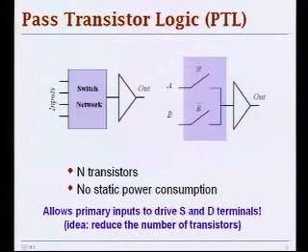So last time we talked about using transistors as switches. We already knew that pass transistors behave as switches, and we're pretty much switching VDD and ground to the output. So why not switch some other value to the output instead of just VDD and ground? As you can see here, we can save a lot of area. You don't really have to create that P network. You just have to create an N network to implement your logic. Anyway, the P network, the pull-up network in static CMOS, is redundant. It implements exactly the complement of the pull-down network.